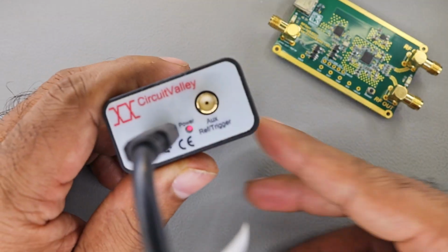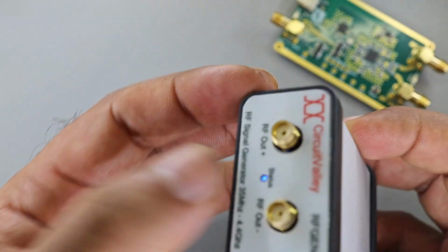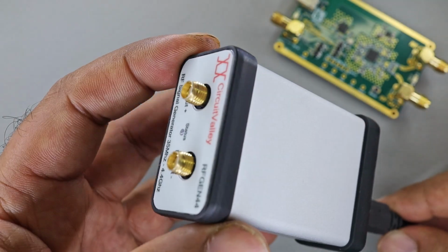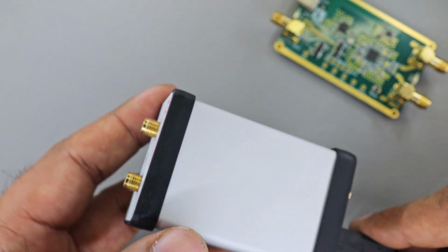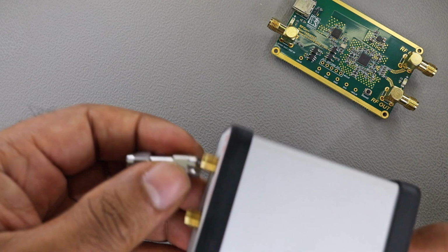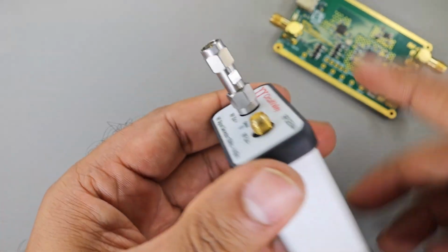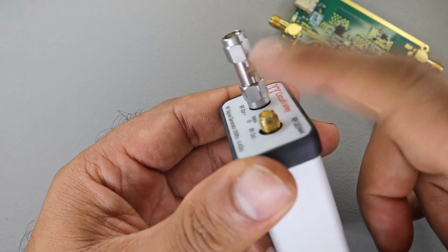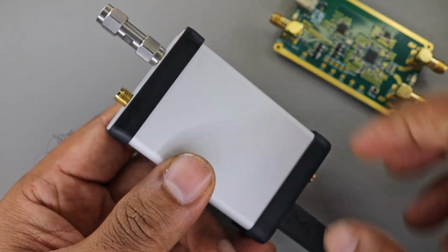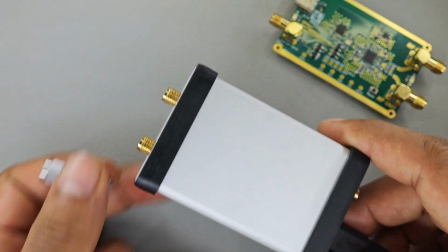So these are the status LEDs, the power status LED, and in front you got the PLL lock LED. When the blue is lit up, you have PLL lock on the output signal connectors. You can of course connect various kinds of adapters to it, for example, this SMA to SMA adapter to convert into various forms. There is enough place between the connector and the plastic housing, so you can connect any kind of adapter or do whatever things you want to do. Both of the outputs are 50 ohms output, so very well suited for any kind of application.